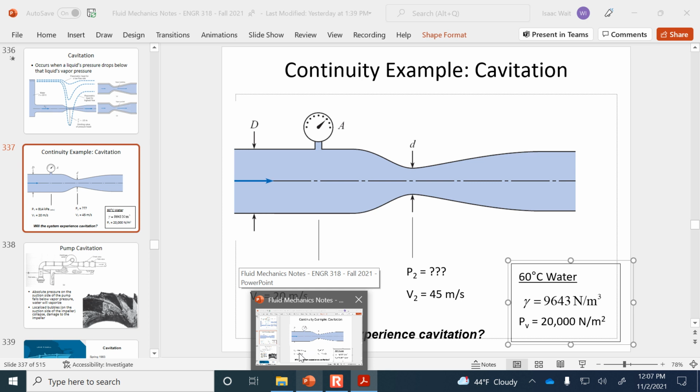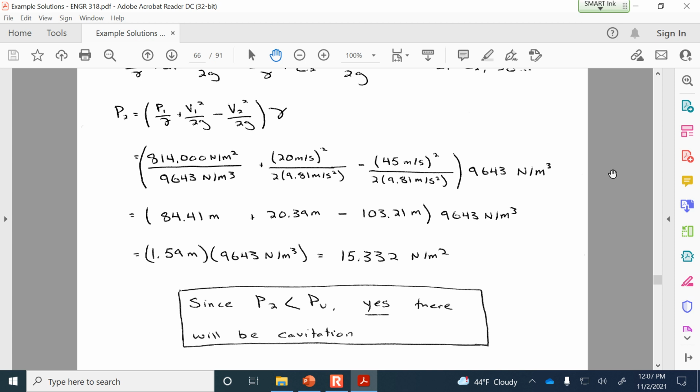Because if you're using a pump to suck water from a source and then increase the pressure and pump it out towards, let's say, houses downstream, then the pressure is decreasing in the direction of flow. And you'll have a low point just right before the pump. And then as the pump is spinning, the suction side of the impeller blades has a little bit even further drop in pressure. So we'll go through some calculations next semester in CE 331